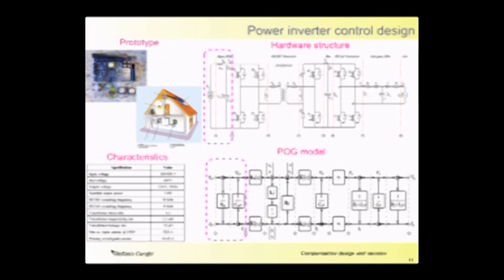The first section denotes the input panel and the input filter. Then we have the DC-DC converter. This is a single-phase converter, and it is composed of an input full bridge connected to an active half bridge through a high-frequency transformer.